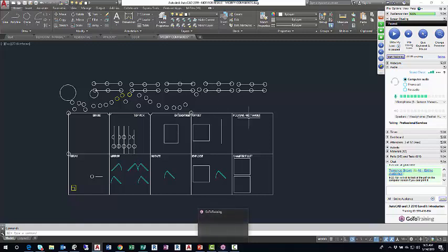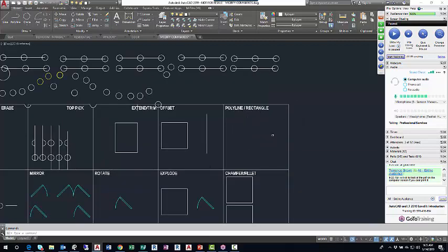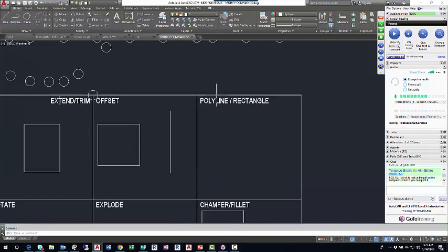Polyline, really the workflow, a term that I hear around AutoCAD, is sort of the starting of the command and the process of moving through the command. The workflow of Polyline is really similar to the line command. With line command, if I start line, the command prompt at my dynamic input at my crosshair says specify first point. I'm going to escape out of that, and this time I'll start the Polyline command. Left click Polyline, and the command prompt says specify start point. So it's one word different, but the meaning is sort of the same.